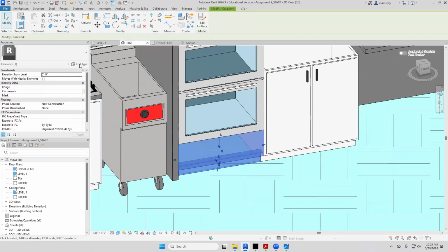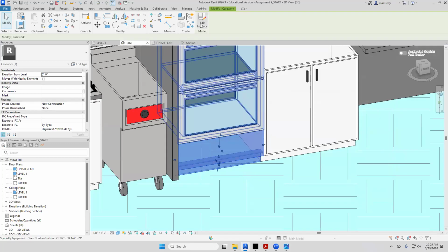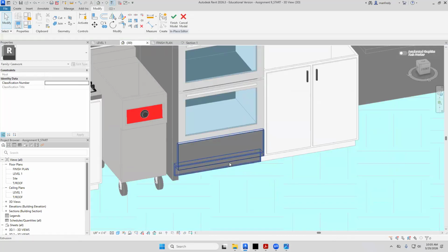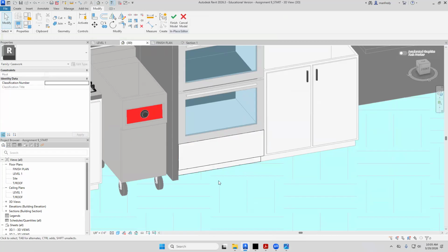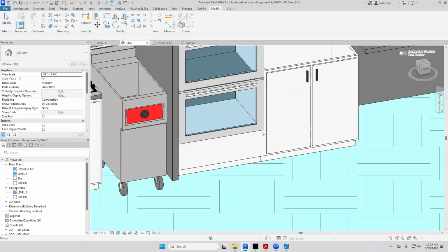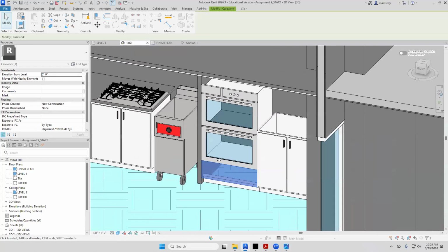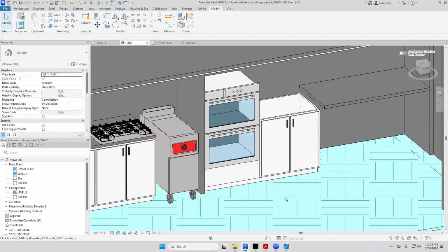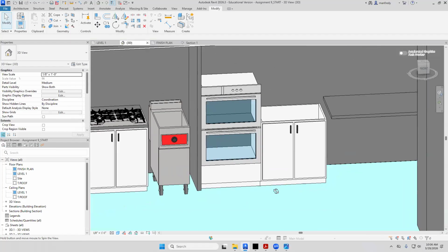No, it did not. Let's see here. Actually, what you do is you click on it, go edit in place first. Then when you touch it, there's the material there. Paste it there. Hit apply. There. Accept it. Accept it. And now you got that cabinet. That could become another cabinet there. So sometimes you have to build things custom in Revit to make them work.